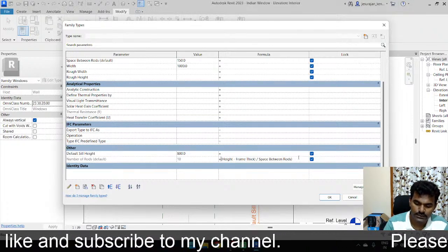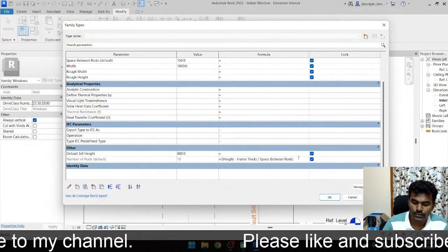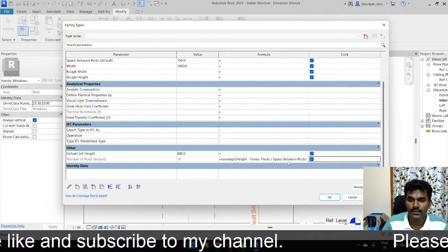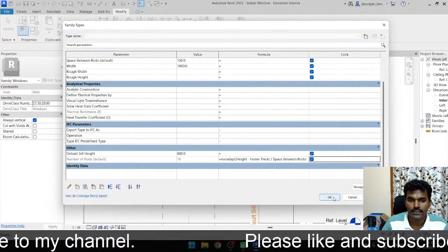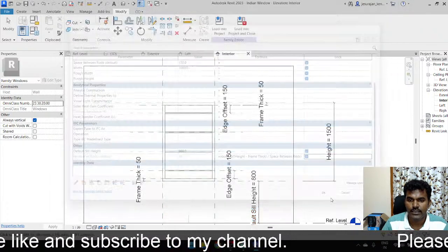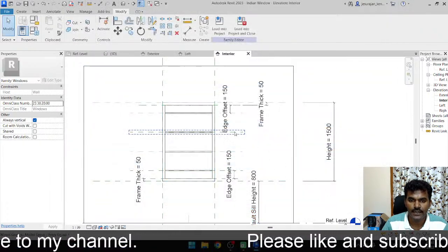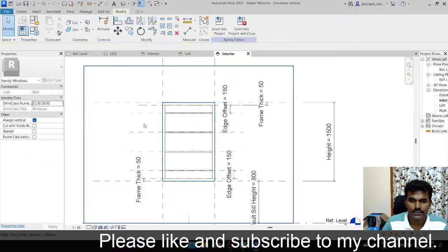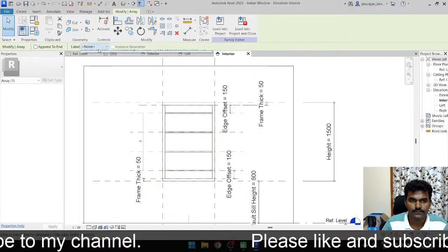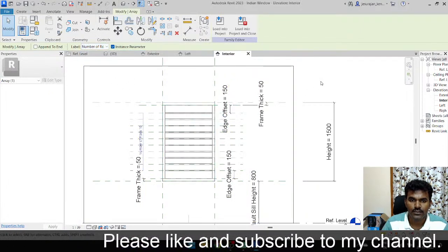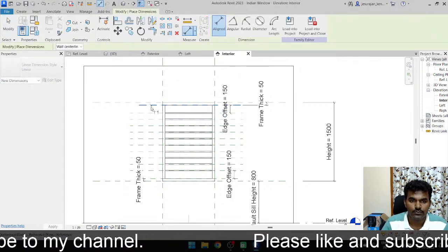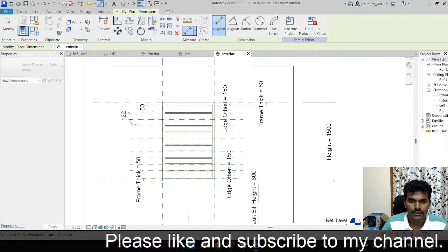Okay, so inconsistent unit means for this close parenthesis. Sometimes, see here, I just did open parenthesis and close parenthesis, then it works. And this is calculating number of rods equal to 100. Say okay. Now you can apply the same parameter here for this array. Select and apply. You see here the number of bars are ready now.